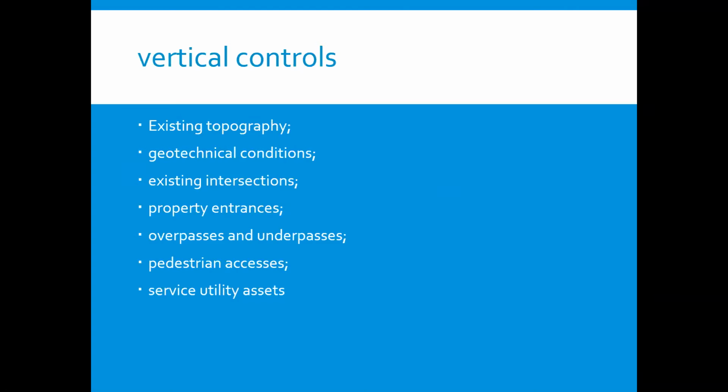Vertical clearances, both to objects over the road and to provide cover to objects under the road, are also vertical controls and must be considered for the whole road cross-section. Changes in crossfall or superelevation, position of the road crown, addition or removal of traffic lanes, and the angle between the road and the object can all have a bearing on vertical clearance and must be checked for compliance with the clearance standards. The impact of future surfacing requirements on vertical clearances should also be considered.